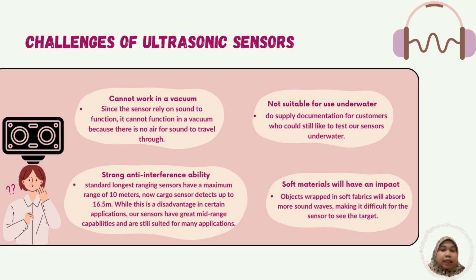Okay, next, challenges of ultrasonic sensors. First, cannot work in a vacuum. Since the sensor relies on sound to function, it cannot function in a vacuum because there is no air for sound to travel through. Second, not suitable for use underwater.